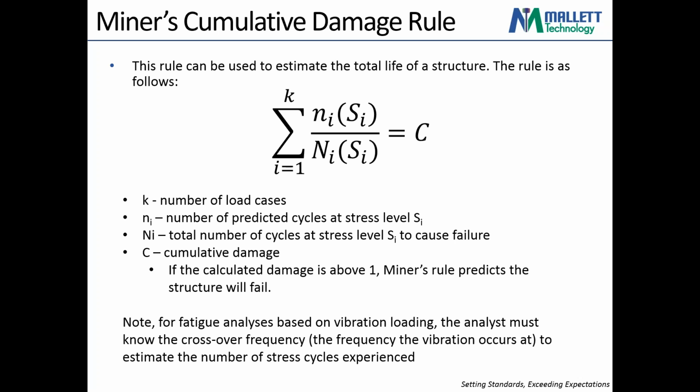And generally, let's say I go through my random vibration simulation, extract the forces, do all the stress calcs, and go through Miner's rule and find that I have a cumulative damage factor of 0.5. That's equivalent to a safety factor of 2, or if the test I was referring to is 5 hours long, that essentially indicates that, hey, your structure is going to survive for 10 hours in the test conditions.